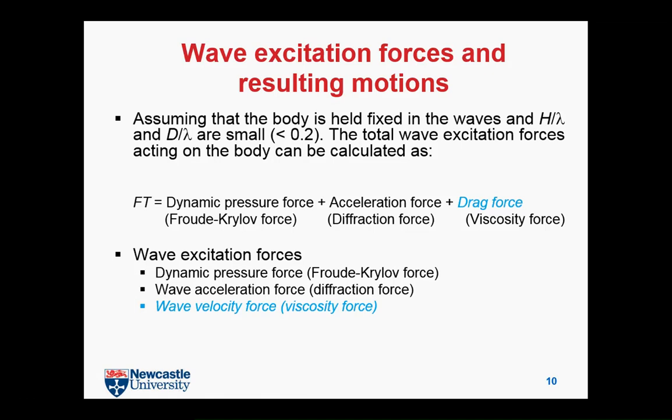When we do the estimations for the interaction between wave and structure, we actually have three parts if we divide the force into different categories. The first one is from your table, you have the pressure expression, right? And for that pressure, you have a static part and a dynamic part.